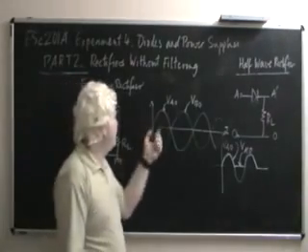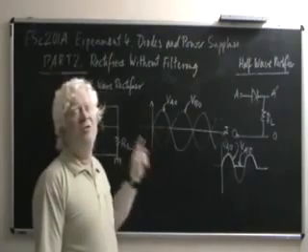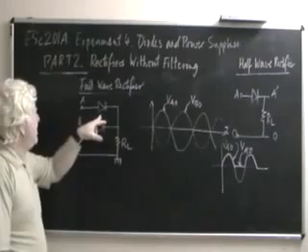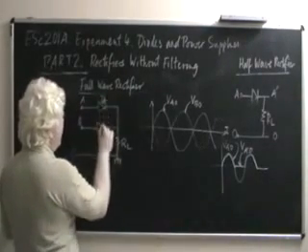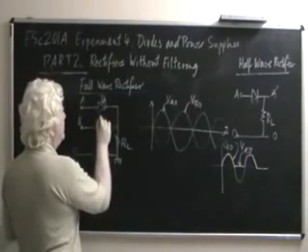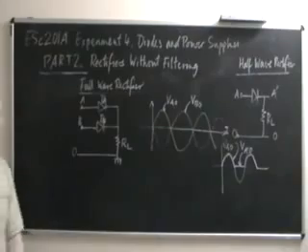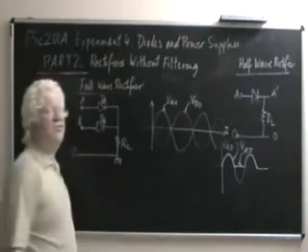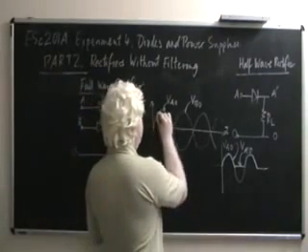In one half of the cycle, the terminal A is positive with respect to O. At that time, this diode turns on, which I will call DA, and this diode is off, and this diode I will call DB. So, at the output, across this load resistance, you will see a waveform that goes like this.